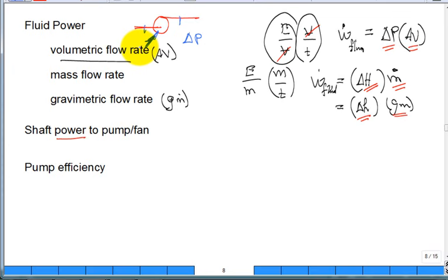So we have some efficiency of the pump, which is the ratio of what gets into the fluid divided by W dot into the shaft that drives it. Now, if you had a motor, you would just back it up and say, I'm supplying electric power. The motor tries to convert all that electric power into shaft power. I have another efficiency of the electric motor, and you can stack those efficiencies. So we have the pump efficiency there.